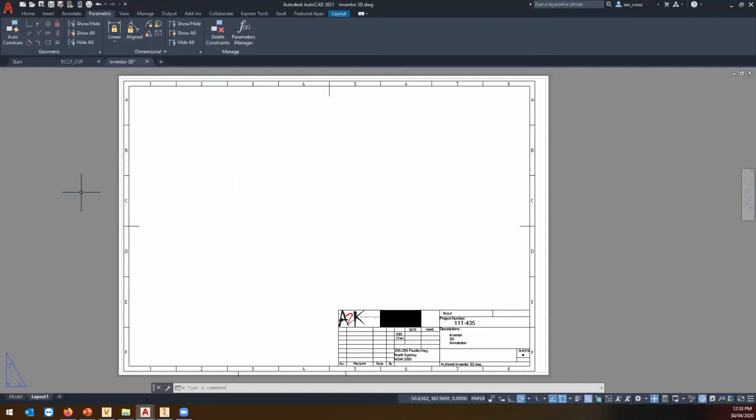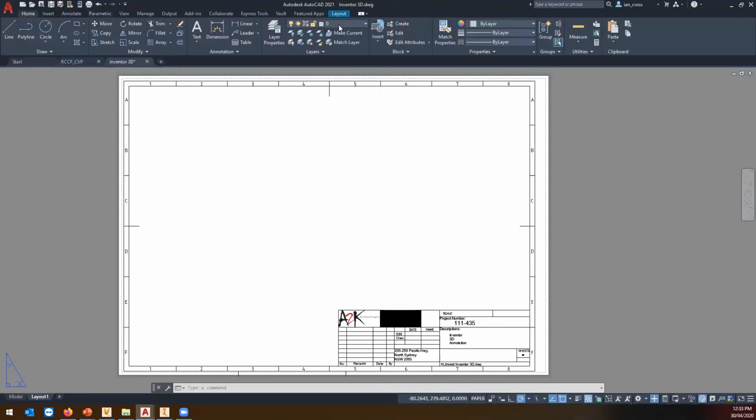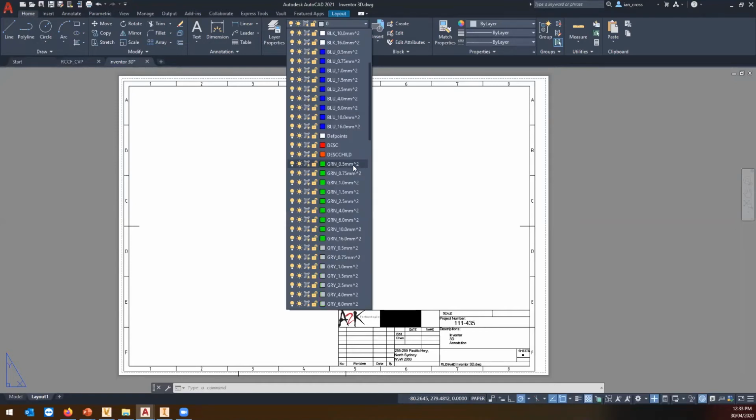Now, all my pre-work involved is I opened up my template and created a very simple 3D shape, and that allowed me to create these two layers, okay? MD visible and MD hidden. Obviously, MD hidden is your hidden layers. Your visible is your visible layers. I have a whole heap of other layers in here, that's all my AutoCAD Electrical layers, because this is one of my AutoCAD Electrical templates. But the main ones we're focusing on here are the hidden and visible.